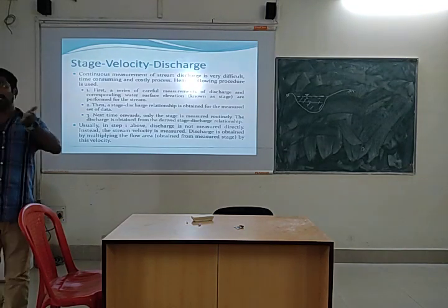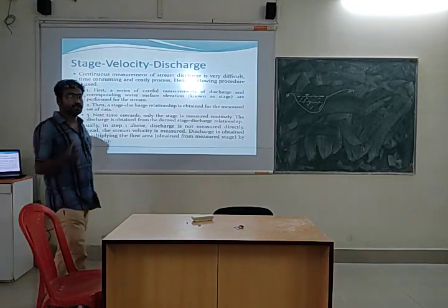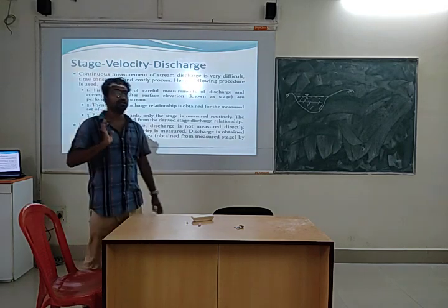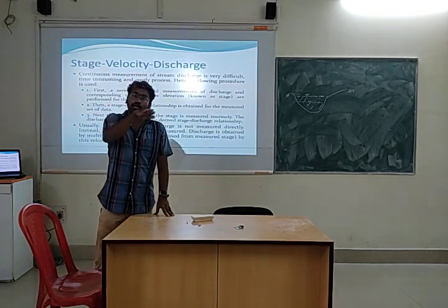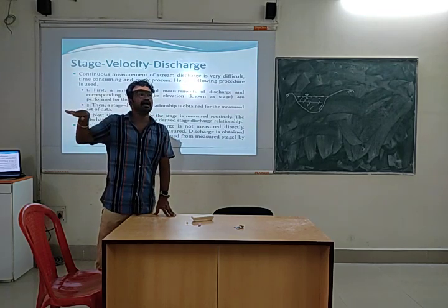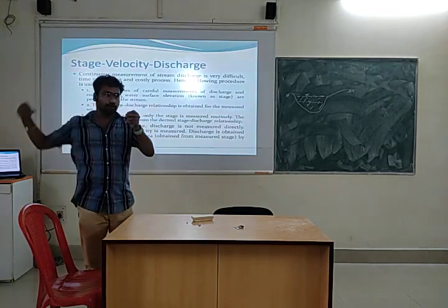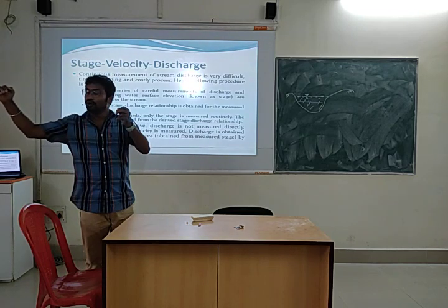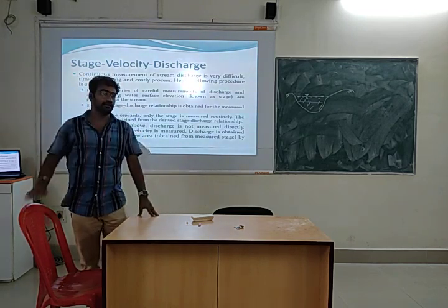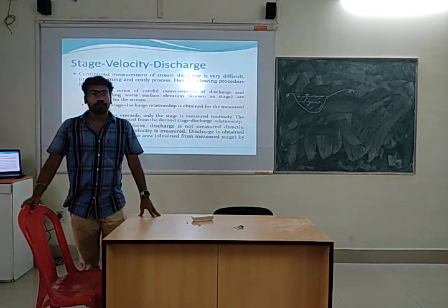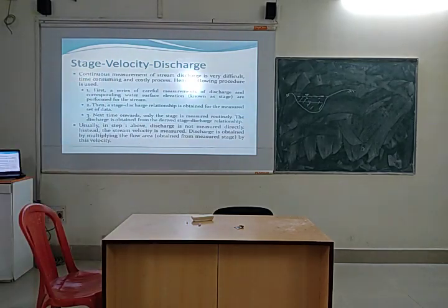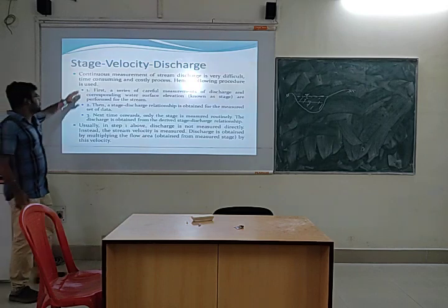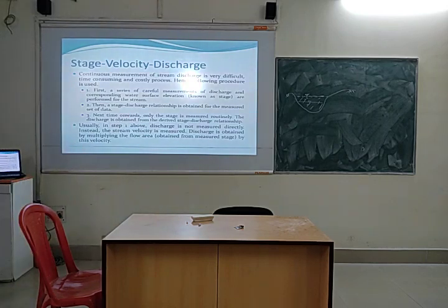Because we are creating the stage discharge relationship, from the next time onwards we will only find out the stage, and from the plot or from the relation we can see what will be the discharge against the stage. Clear? Clear now? Okay.